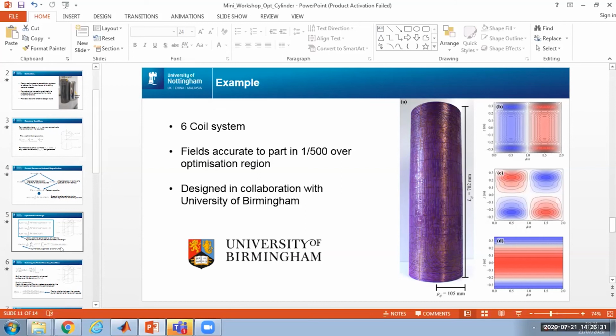To answer the question about multiple layers of shielding, you don't see any of the multiple layers. One layer is sufficient to satisfy the boundary condition well enough that you don't see any change from subsequent layers, no matter how many you have. Okay, and I realize that when people talk about different layers of shielding, typically a layer is a composite of many laminated pieces, which is what I was referring to.